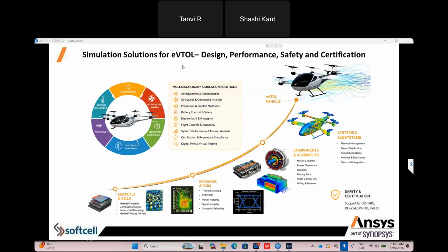So we have Ansys ACP, Ansys Composite PrePost. So this composite module can help you to develop composite material, and you can define the number of layers. You can even define the orientation of the fiber. You can define resin material. If you want to see the curing process, let's suppose you are putting it for curing inside the oven, how much time is required for the curing, or you want to see final component compensation.